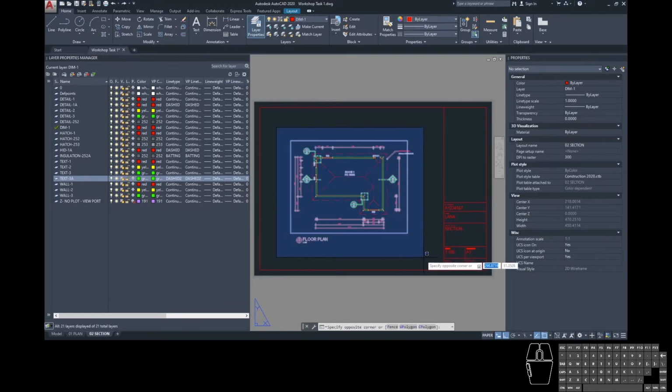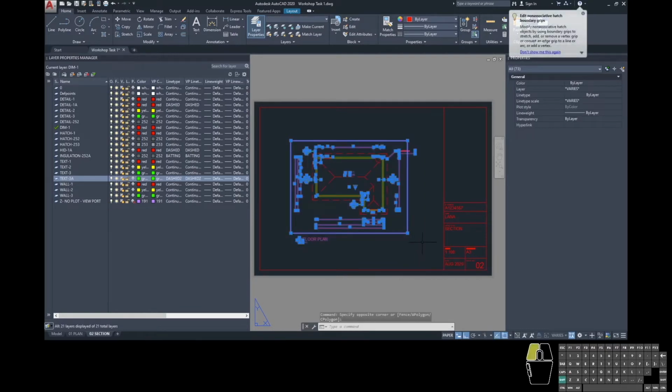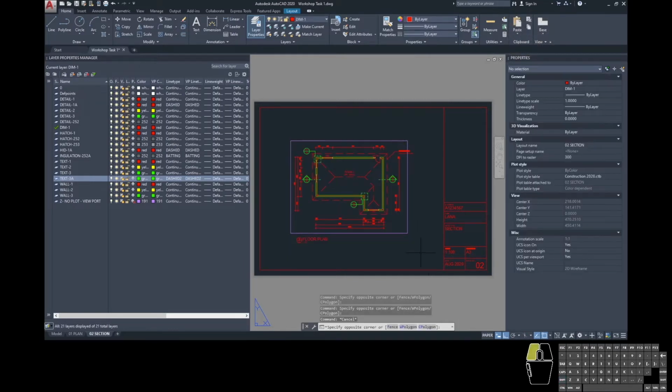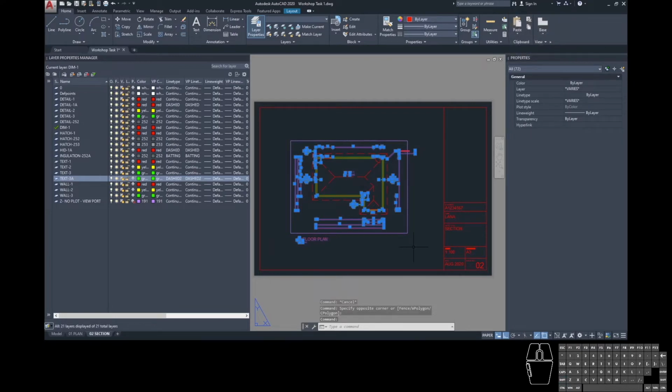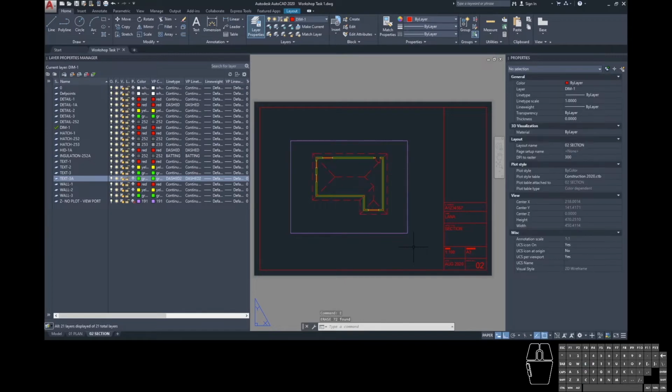they're not applicable. So I'm going to select everything that's here, but I'm going to hold shift and then click on that viewport to deselect part of that selection. So when you've selected a heap of stuff, if you want to remove something from that, you hold shift and then click on it, and it will remove that item that you're selecting with the shift click. We can then hit erase, and that clears all of those annotations off.